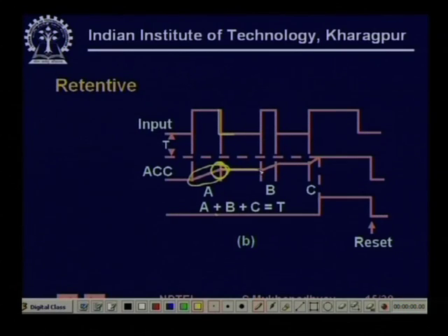As long as the input is 0, it is held. For the next pulse, it counts from the previous value. That is why it retains its timing register value, and that is why it is called a retentive timer. Finally, as this increases, at some point, maybe for the next pulse, it reaches the preset value, and at that point the timer goes high. So, this is the semantics, or meaning, of the way the retentive timer works.